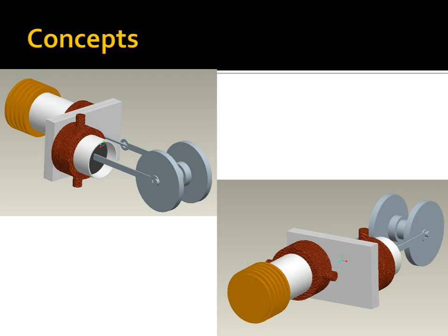So there needs to be tight tolerances there, in terms of a tight seal, and as well there can be very little friction, and the shafts have to be lined up. That said, also the power piston needs to have a relative smoothness and flatness. It has to have a straight cut in order to provide the seal. Also, the grooves and the rings around the power piston will help achieve a solid seal.